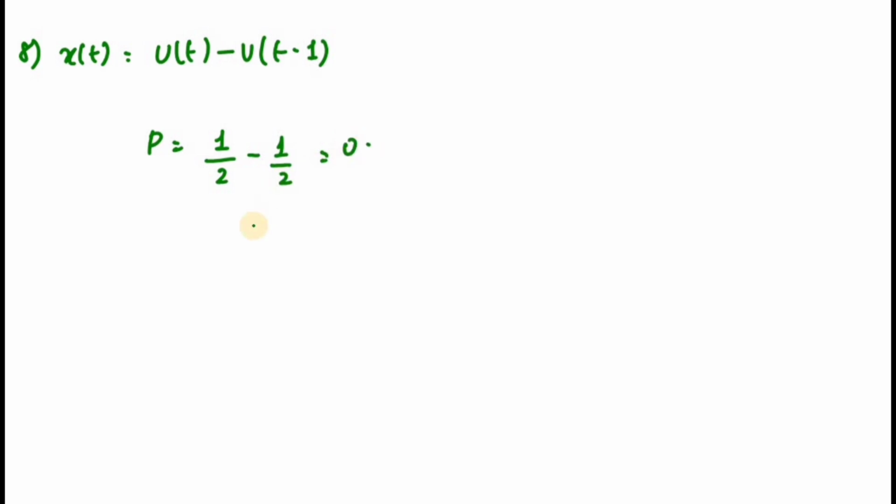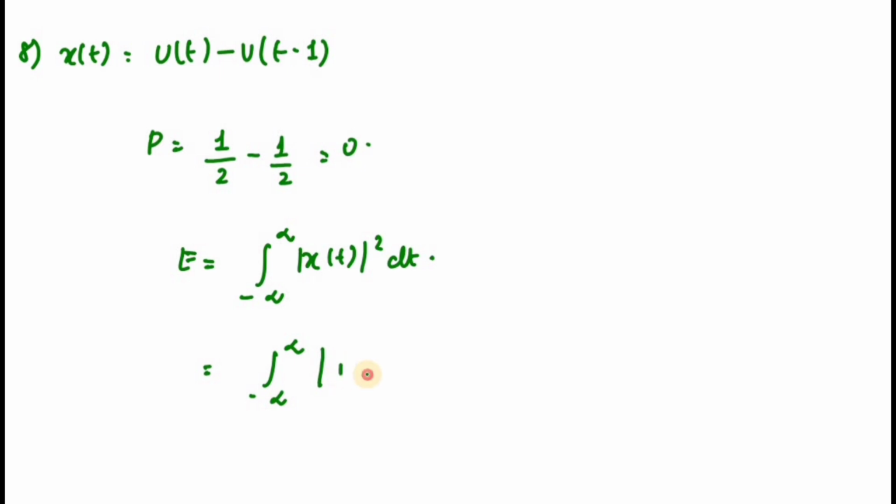Therefore it is definitely an energy signal. The formula for energy is the integral from minus infinity to infinity of x of t whole square dt. So if I solve, first I write the integral of u of t square dt minus the integral of u of t minus 1 square dt.